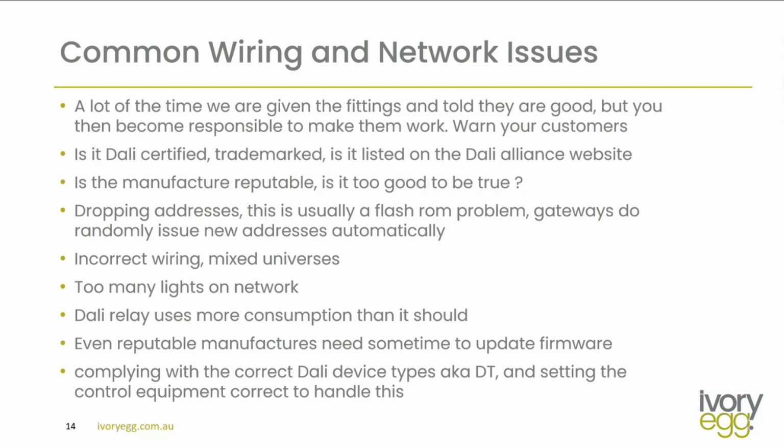Even reputable manufacturers sometimes need to update their firmwares, and the other thing that's really important is, have you got the correct control equipment to match your DALI type devices? What I mean by that is, have you got DALI type 8 fittings or color control fittings or exit emergency fittings, and have you got the right corresponding gateway or DALI controller to handle this equipment? They've got to be compliant and both up to that kind of standard for it to work. A lot of the time you'll find it'll work, but it'll only work at a basic level.